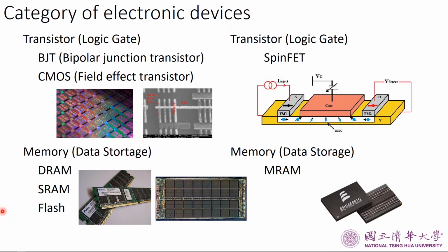On the right-hand side shows the device that takes advantage of the electron spin property, which is known as spintronics. Similar to the MOSFET, which uses charge to control the gate, spintronic devices use the gate to tune the electron spin direction in the channel, and the metal contact at the drain will detect the orientation of the spin electrons, causing different resistance. Therefore, we can form a field effect transistor by voltage gating, but not magnetic field.